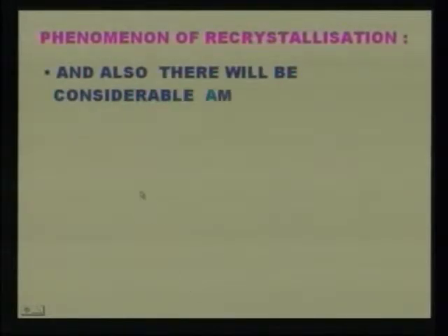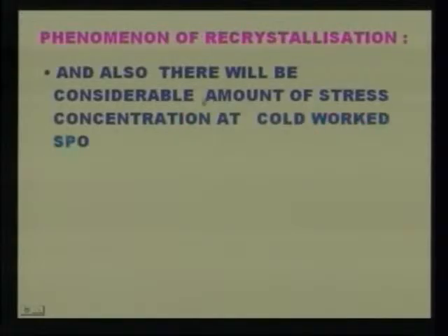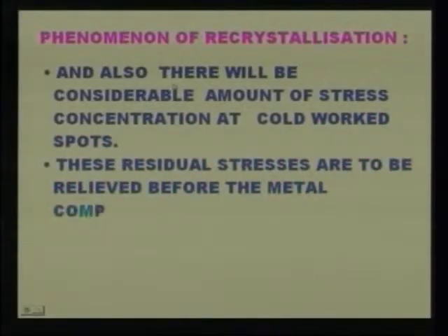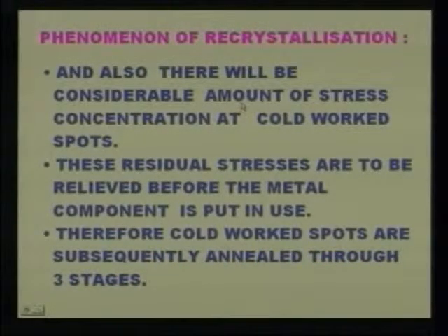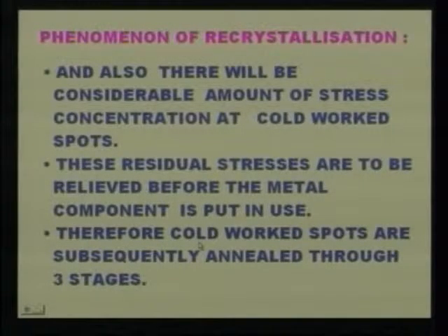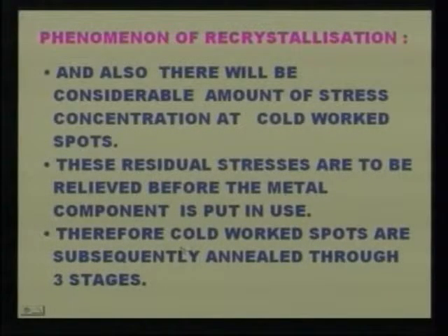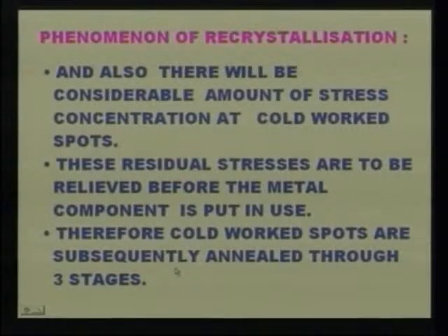Now you see some more points on recrystallization. There will also be a considerable amount of stress concentration at cold worked spots. Now see another point: these residual stresses are to be relieved before the metal component is put in use. Therefore, cold worked spots are subsequently annealed through 3 stages. Let us see what the stages are.